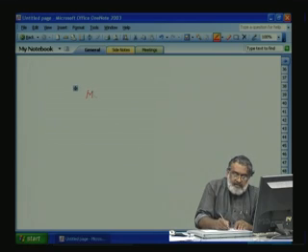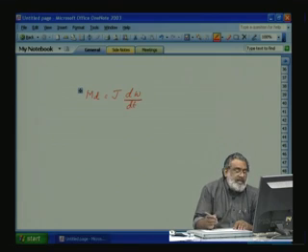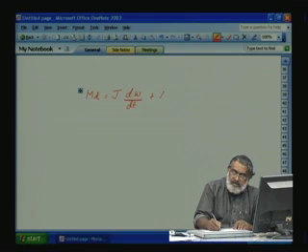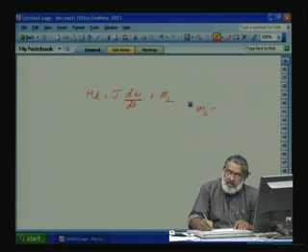So, driving torque MD is equal to J into d omega by dt, that is angular speed in radians per second, plus our load torque. Here ML is the load torque in Newton meter.